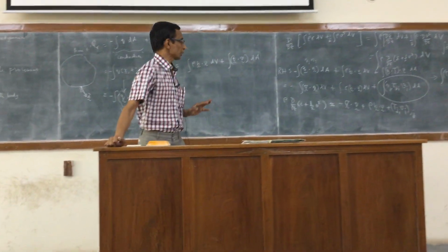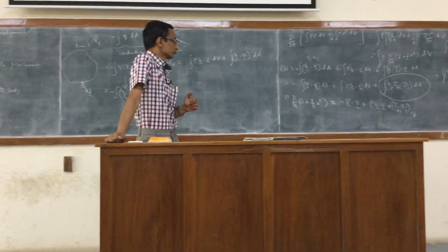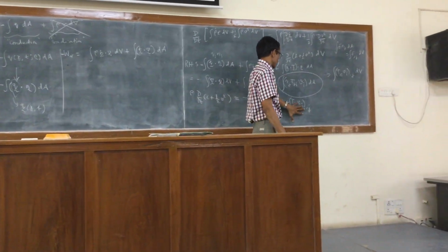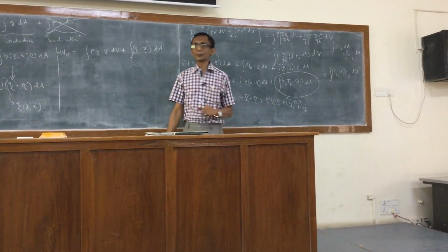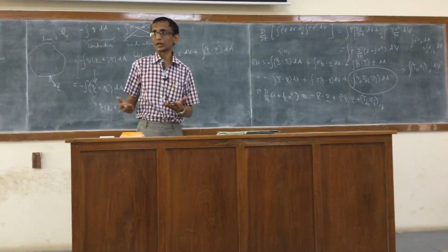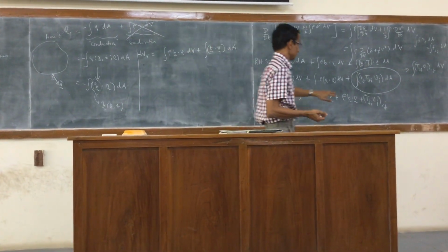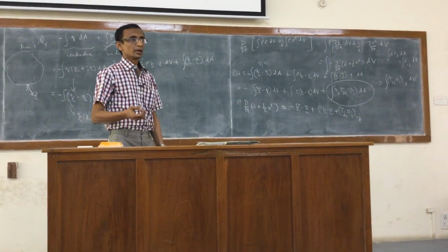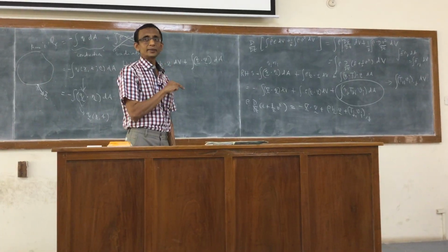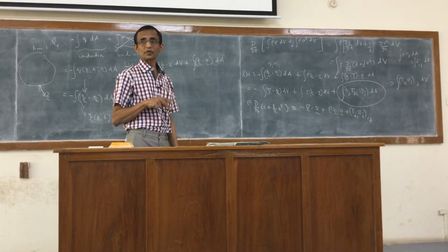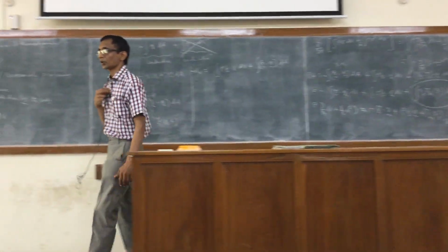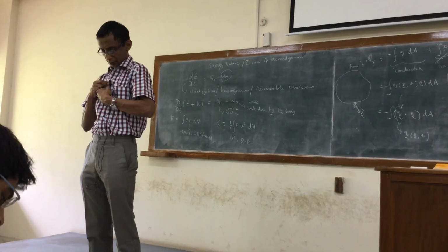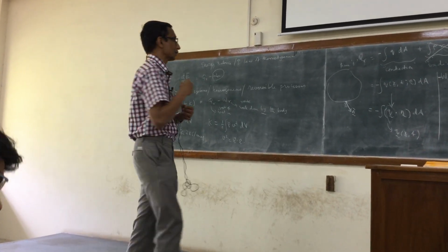This is not a very commonly reported form because of the somewhat problematic, not problematic, there's no clear-cut physical interpretation of that term, which I have to leave as it is, t_ji v_i comma j. So we won't examine this now because I'm going to write the first law of thermodynamics in a slightly different form, which uses what is called the mechanical energy balance. So we'll write down what the mechanical energy balance is.